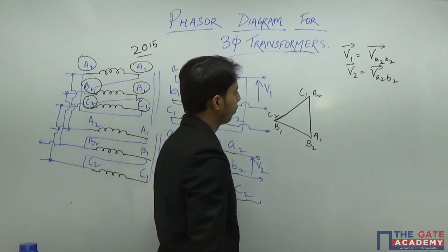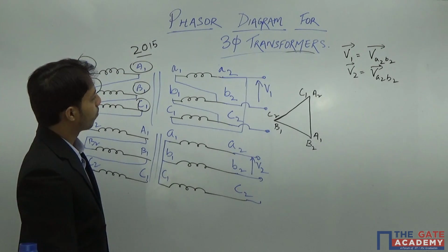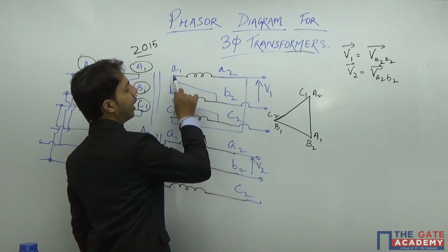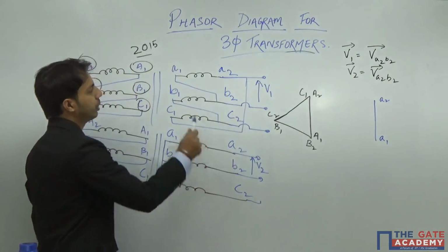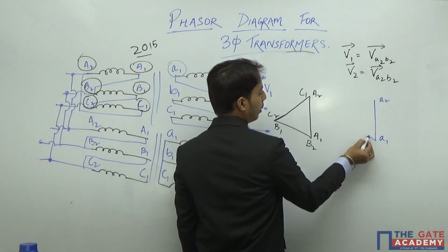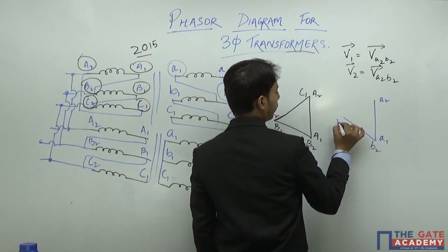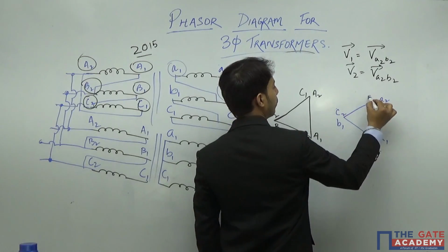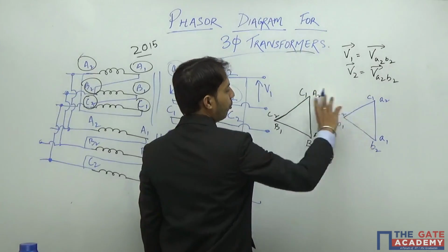Okay. So now let us see what is the connection in the secondary. In the first transformer, let us draw it with some other color. That is the first transformer secondary. I have connected A1 with B2. So you see, this is my A2, A1. Now I am not going to change the alignment again. I am connecting A1 with B2, and I am connecting C2 with B1. That means this first transformer secondary has a similar, or 0-degree, connection with respect to the primary.